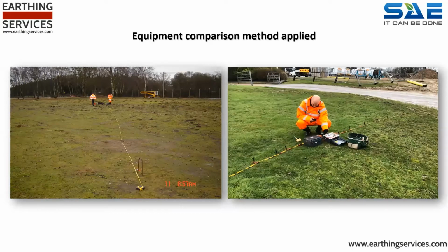For a given soil resistivity survey, we recommend a number of routes are adopted to ensure that the data is verified as representative, and where possible, that 2 test instruments are used for each activation distance to ensure that the test instruments correlate. Some companies do not reference measuring tapes, instead relying on engineers pacing out the distances, which is unreliable. Furthermore, some companies only undertake a single route, a further compromise as there is no verification of the data set obtained. Most companies do not use multiple test instruments.